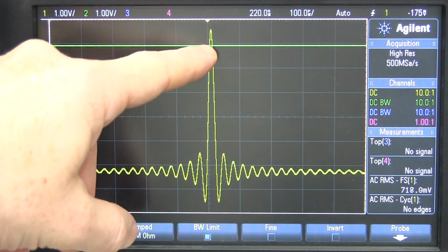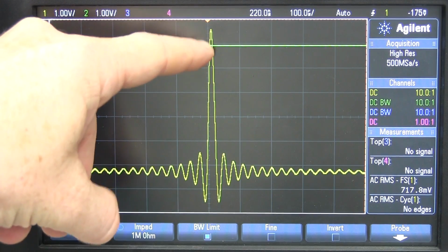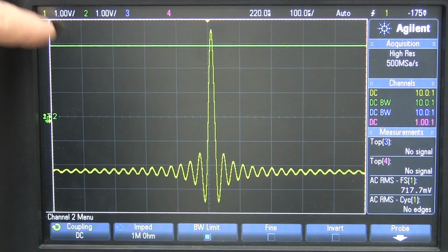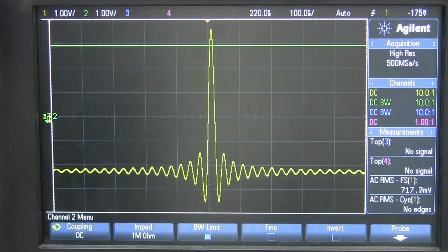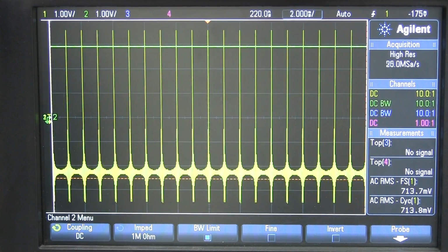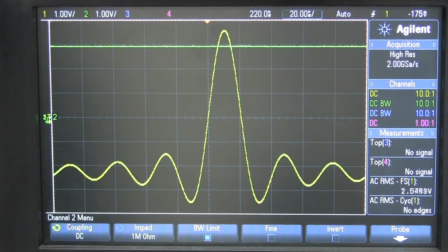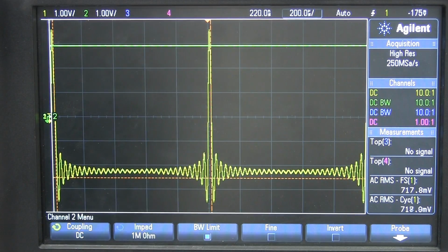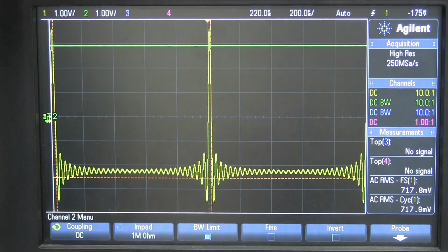We're getting our 1 diode drop in there. You can clearly see that around about that 0.6 volts. We're both 1 volt per division there. And there's no droop at all because there's basically very little load on our capacitor. The only load, of course, is the 10 meg input impedance of our scope probe.